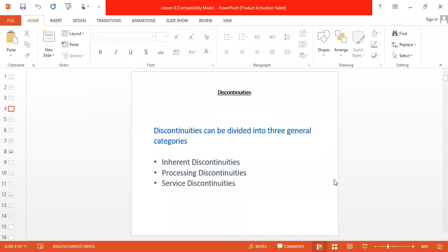And the third one is defect. Defect means again the continuity broken or indication which will affect the life of the job or the performance of the job, then we can say defect. So there are three types of discontinuity, based on the processing stage of manufacturing. One is inherent discontinuity, second is processing discontinuities, third is service discontinuity.